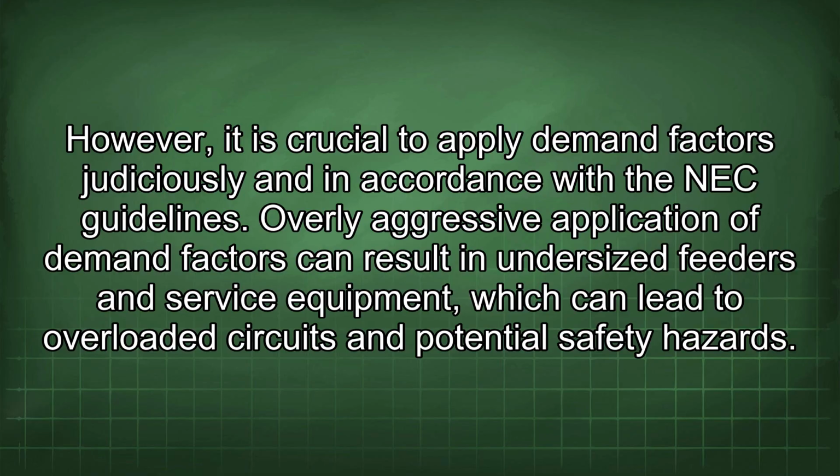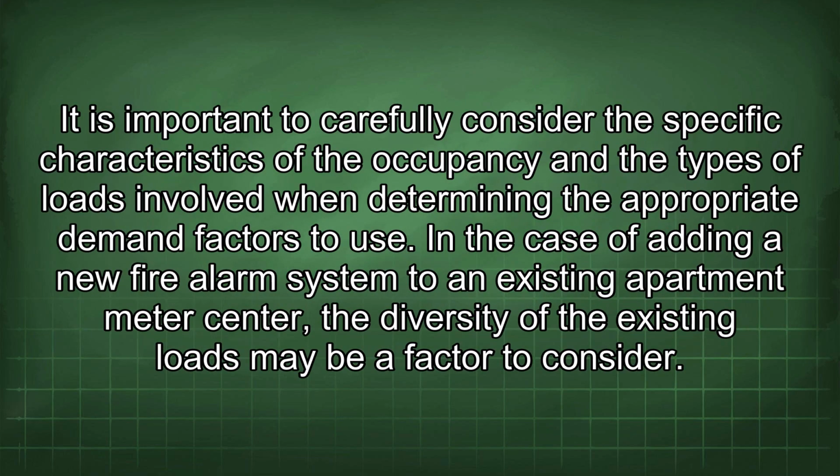Overly aggressive application of demand factors can result in undersized feeders and service equipment, which can lead to overloaded circuits and potential safety hazards. It is important to carefully consider the specific characteristics of the occupancy and the types of loads involved when determining the appropriate demand factors to use.